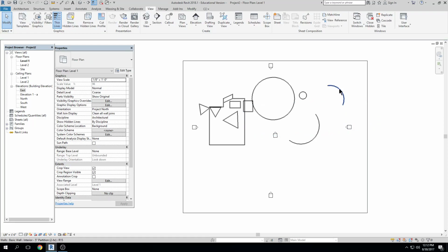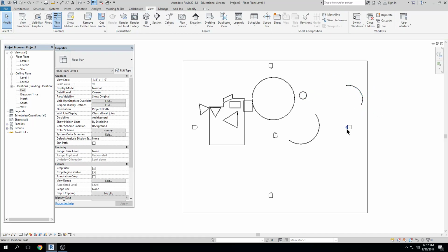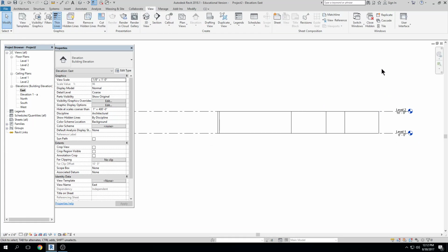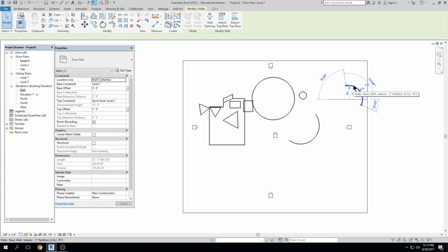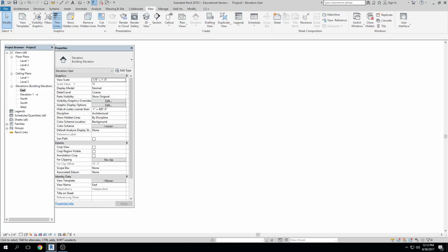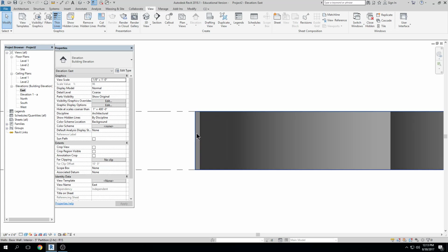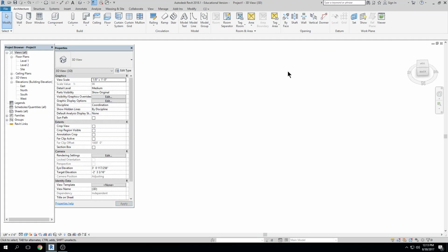So if this wall, for example, I nudge it over so it's out of that boundary, or maybe slightly out of the boundary, then it wouldn't show. Well, it doesn't matter anyway, because you can't really tell which is which in that elevation. But let's see if we can get it to cut it. Maybe it'll look a little weird if it cuts it. I can double click on this little marker too. Click, click, really fast. I'm going to shade. Let's figure out, I'm going to do a wall tile or window tile. Wall tile. Hold on a second.